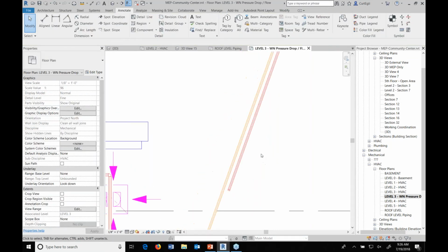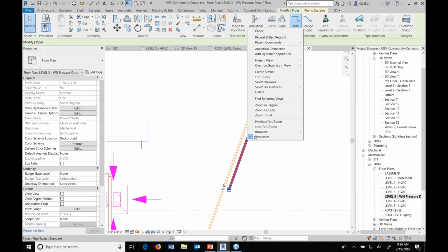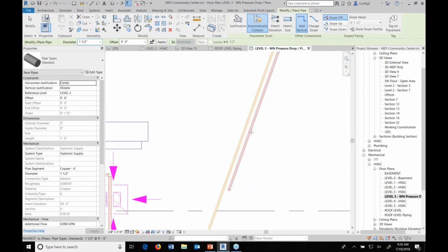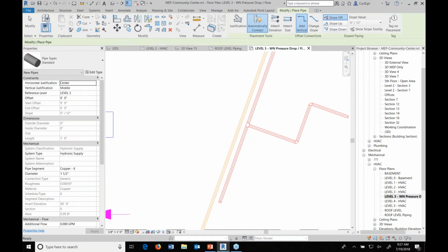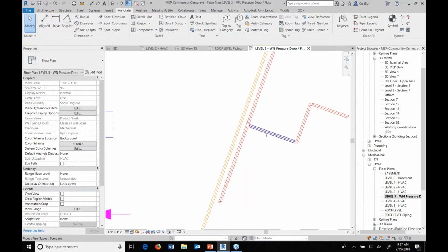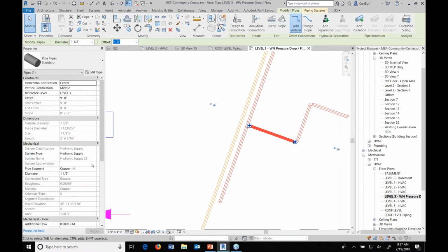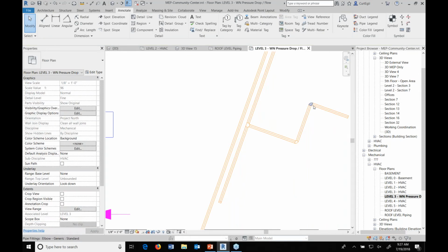So say that I create similar off of this, and I'm drawing some pipe here, coming off perpendicular. When you change, for those of you that don't work with pipe or MEP land, if I were to take this red one, which is hydronic supply, and say that it's actually hydronic return, it's a cascading event, which is a good thing, because then you don't have to go around from fitting to fitting and say you're actually part of a different system here.